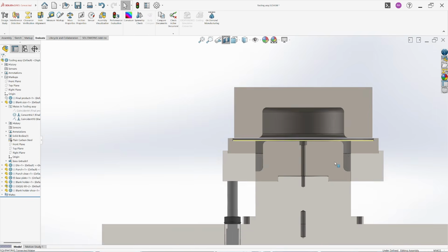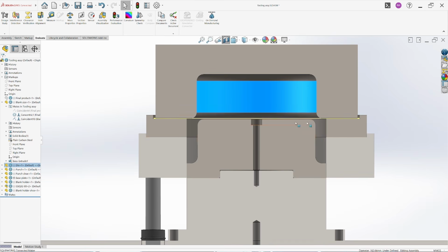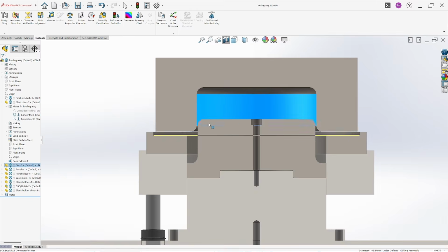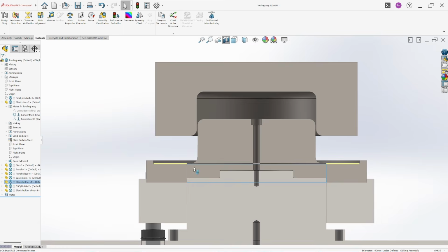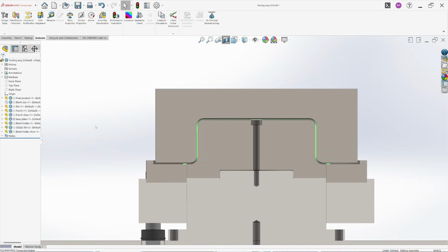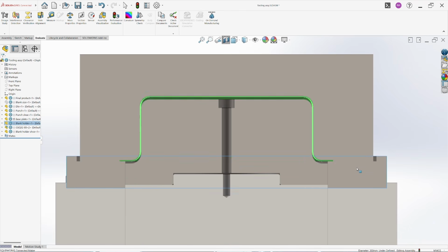why not mate it with that blank holder, right? So yes, now the die will start forming the blank size, and this blank holder will go with the die, and this will be formed like this. And when it reaches its end position, at this time the blank size is completely deformed into our final product, the container form, something like this.